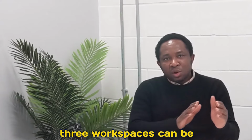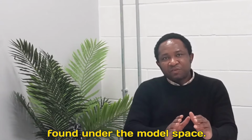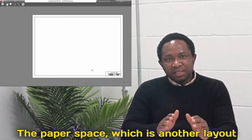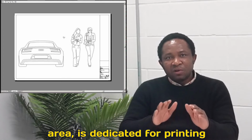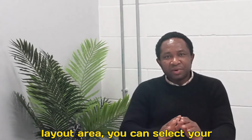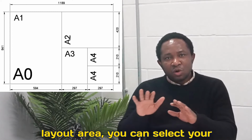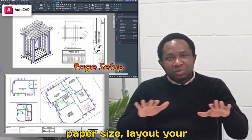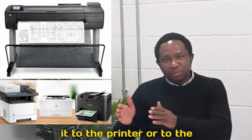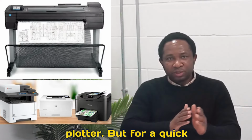These three workspaces can be found under the model space. The paper space, which is another layout area, is dedicated for printing purposes. In the paper space layout area, you can select your paper size, lay out your drawings as you want before sending it to the printer or to the plotter.